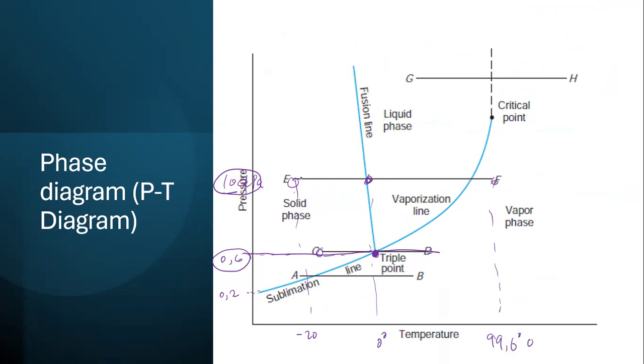So that means from solid at high pressures, from solid through the fusion line, this is the equilibrium. This is where the composition of saturated solid and saturated liquid is equal. Hence the fusion line we call the equilibrium line, meaning saturated solid and saturated liquid are equal at this point in time.